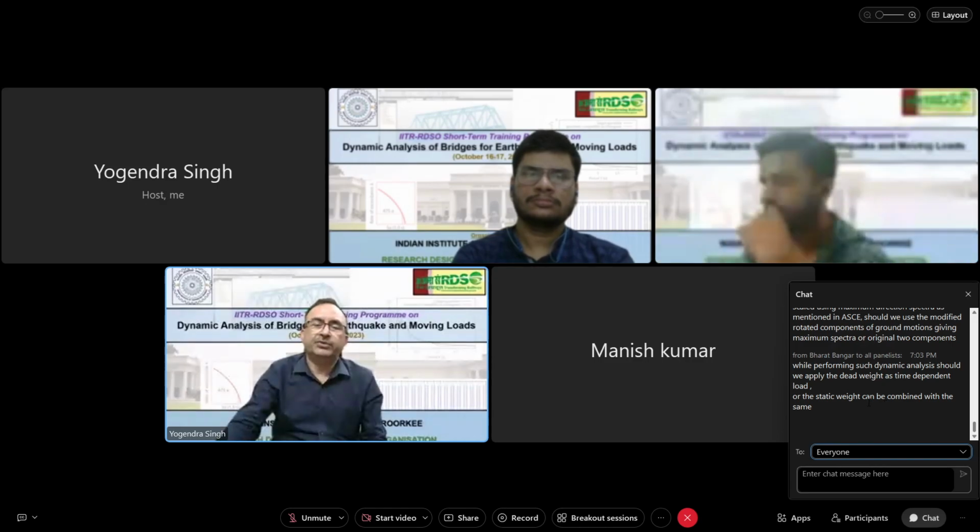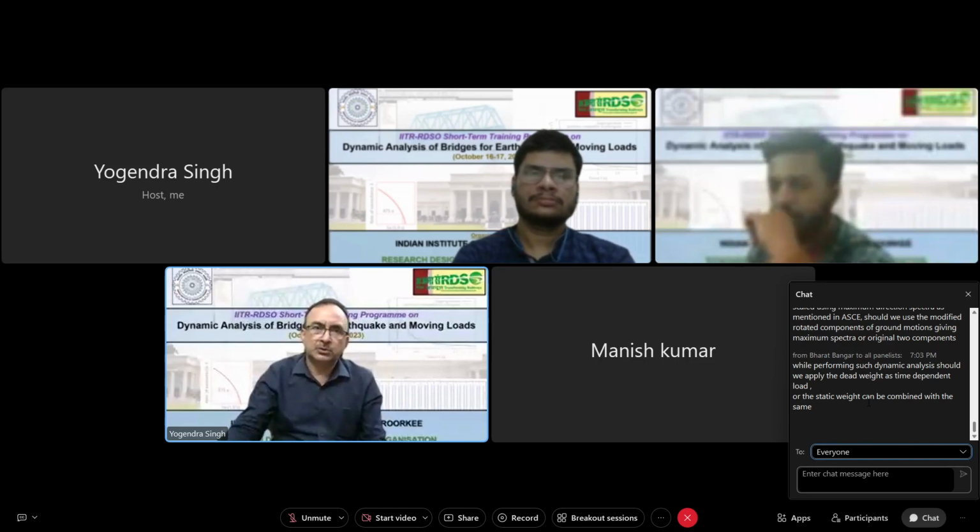Okay, so in linear analysis, if you are performing a linear time history analysis, superposition is valid. So you can perform analysis for that load as a separate static load case, and you can perform the analysis under moving load separately, and you can superimpose the two. Under live load, you can perform a dynamic analysis. Under dead load, you can perform a static analysis. And the results of static and dynamic analysis can be combined for any member or for any node. Even if we are calculating the displacement, we can combine those two.